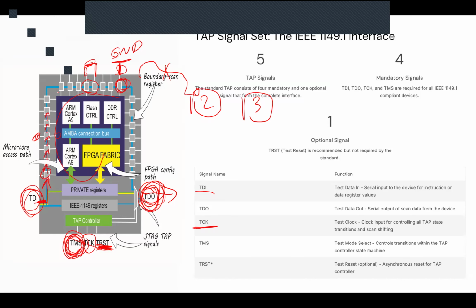Or we are in an observation mode. When we capture, these cells are not bypassed, but they don't intercept the signal and just capture the signal for each clock. The TDO would give us the real-time observation of how our core logic works. So this is the situation.